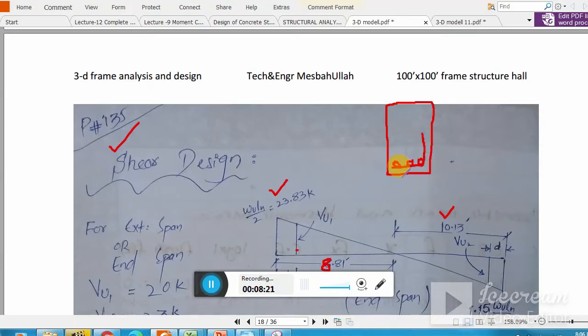When I calculate this, the clear spacing is 1.75 or some 1.5 inches. So number 4 and number 6 bar. When I subtract all these things, I get my d now as 15.5 inch. Remember, you have to check this. It will change when you place your bar. Initially we assumed that we would use this bar as number 8, so that's why my depth has now increased.